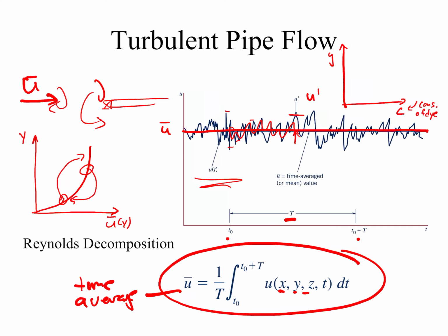So then maybe the concentration looks like this. I have a low concentration, and then boop, I have a high concentration. I put blue dye here, and up here, let's just say for the moment, there's no dye. So this is clear over blue dye. And if all we had were molecular effects like in laminar flow, then very slowly the gradients between the dye would change, and the blue would slowly move up into the area above.